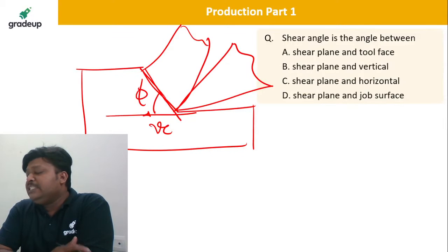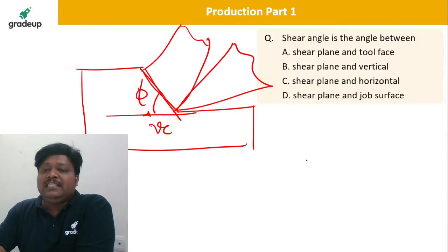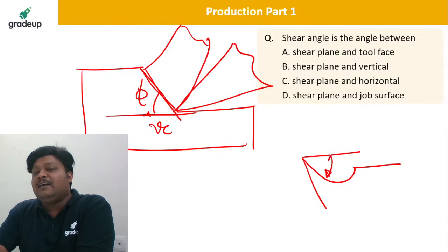So dear Bhupesh, lip angle is again dependent on how much rake angle you are providing onto the tool. So ultimately the rake angle is the main thing. Okay. So this lip angle is going to form when you are making the alpha, and when you are having the relief angle. Please remember, relief angle is not having that much value, 3 degree to 10 degree, that is more than enough relief angle we are using. But this is very important here. This is the decision making angle.